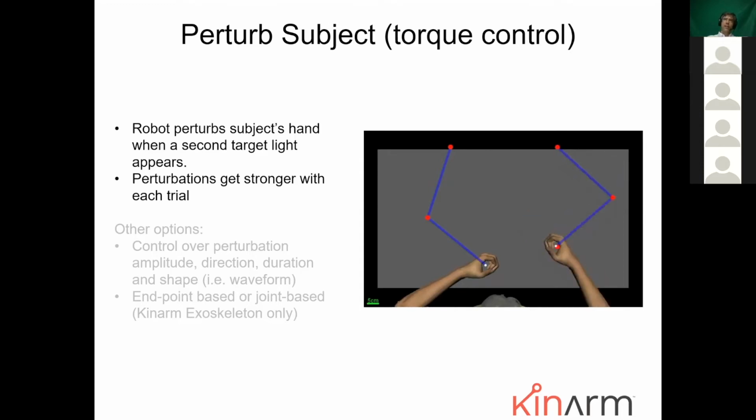So again, with position control, what is being controlled is position. So it's going to make sure that it always tries to follow the same position, and you might get very different torque levels depending on subject behavior. With torque control, the torque levels are always controlled, but the positions might be very different, again, depending upon subject behavior. Does that difference between position control and torque control make sense to people? All right.